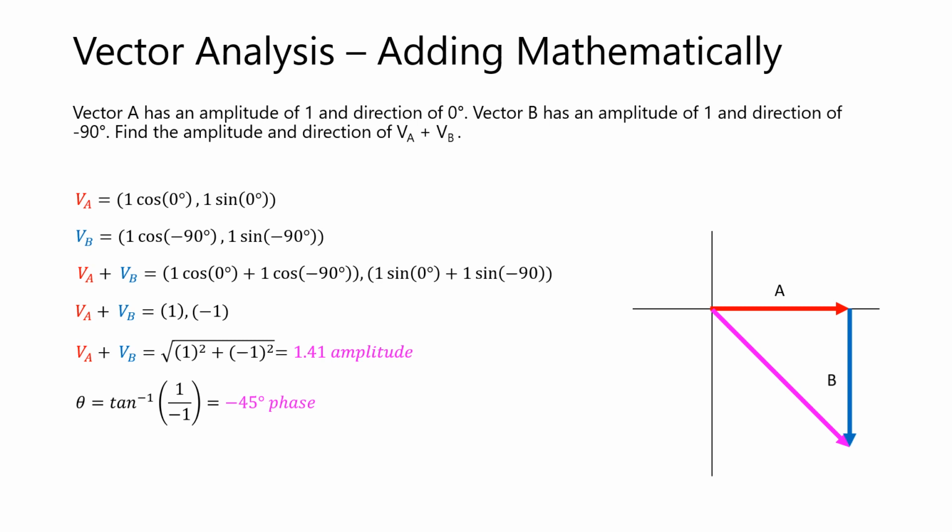Now, a vector line is used to describe two things: amplitude and phase, and we can use them to describe how RF patterns develop, the relationships of the 90 Hz and the 150 Hz signals, and how CSB and SBO signals combined. So let's begin with how the localizer RF pattern is developed.